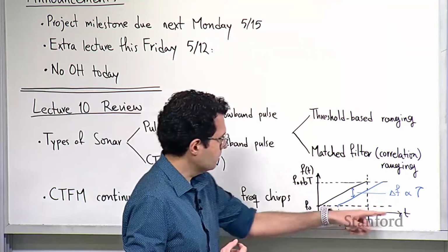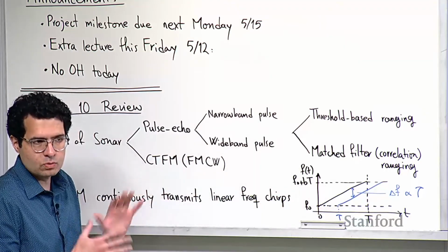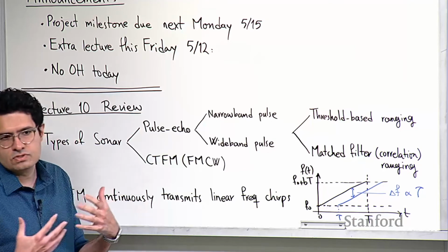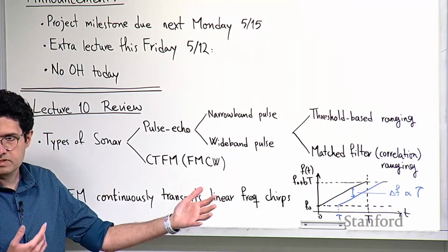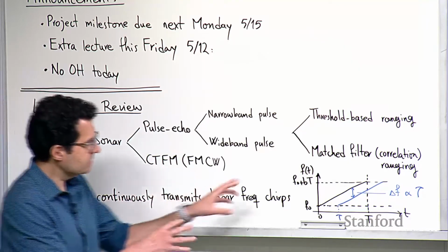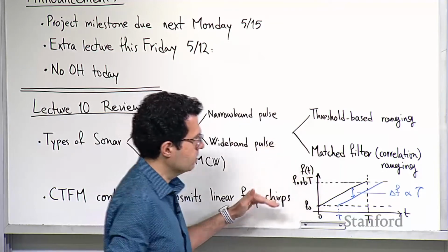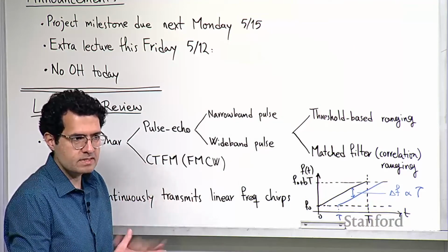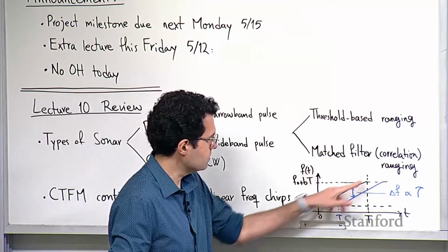So this plot is a bit of an unusual way of visualizing the signal, because either we're used to looking at signals in terms of their amplitude versus time, or we look at their Fourier transform. This is something in between. Your vertical axis is the instantaneous frequency, horizontal is time, okay? But it is the most intuitive way of thinking about these signals. So the instantaneous frequency, let's look at the black first.